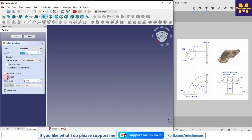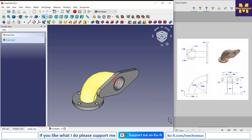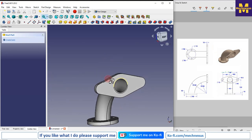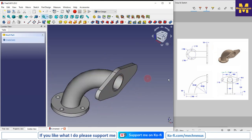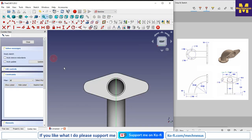So here I will reverse the direction, and the thickness is 10 mm. We'll say OK. So we have made our flange. Now I will add the hole. So for this I will select this face and I will create a sketch.